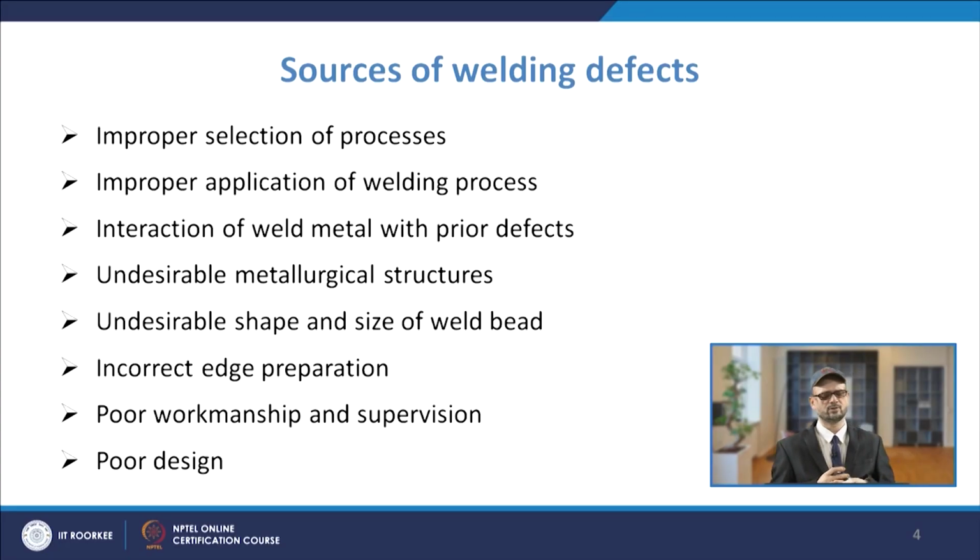Then, apart from this, you have undesirable shape and size of the weld bead, and incorrect edge preparation. First, undesirable shape and size of the weld bead. Here again you will have to look into the weld profile which you are getting.